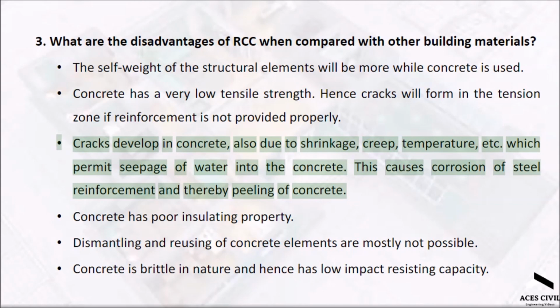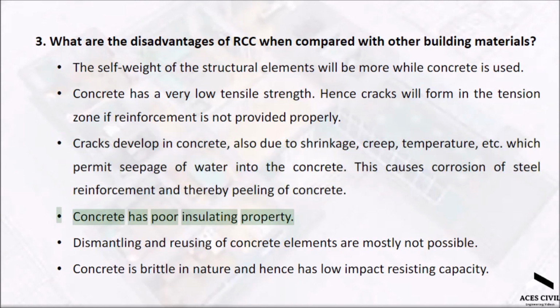Cracks develop in concrete also due to shrinkage, creep, temperature, etc., which permit seepage of water into the concrete. This causes corrosion of steel reinforcement and thereby peeling of concrete. Concrete has poor insulating property. Dismantling and reusing of concrete elements are mostly not possible. Concrete is brittle in nature and hence has low impact resisting capacity.